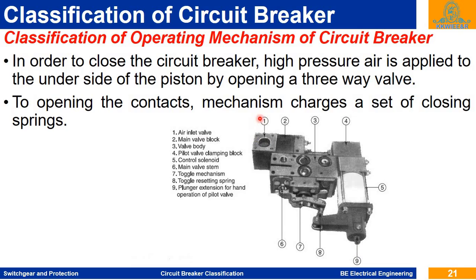Here you can see the air inlet, where pressurized air is connected to this valve. This is the main valve block, this is the valve body, this is the cylinder, and these are the toggle mechanism and resetting springs in this pneumatic system. So this is a pneumatic operating mechanism to open or close the circuit breakers.